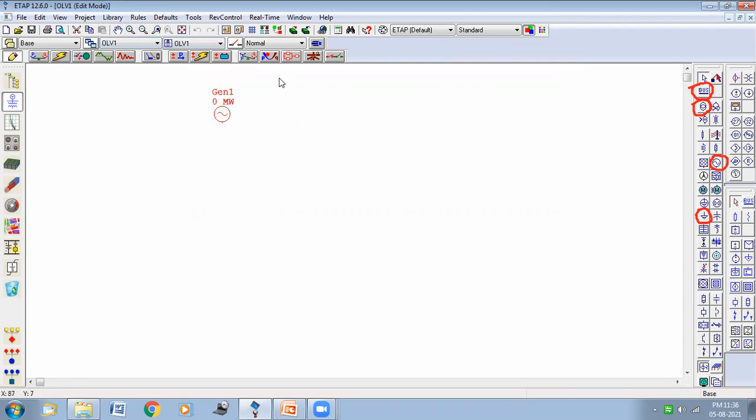Okay. Next, you have to choose the reference bus or swing bus. This is the slack bus, the reference bus or swing bus, you can say. It is essential for load flow analysis. Next, you have to choose the transformers, two transformers for making this parallel transmission line or parallel feeder system. Like this, these are transformer 1 and transformer 2.